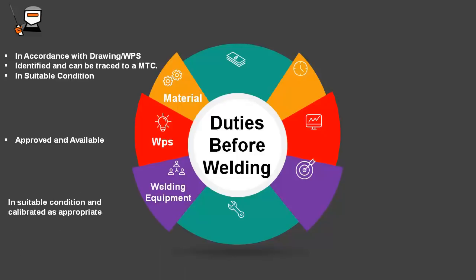Welding equipment. If you are performing welding tasks on welding machines that are out of calibration, they can create an environment where welder errors are possible. So before beginning work on a new welding process, you should have your machine calibrated. Welding experts recommend that your welding machines be calibrated annually. It can help you avoid costly mistakes that could have been avoided.